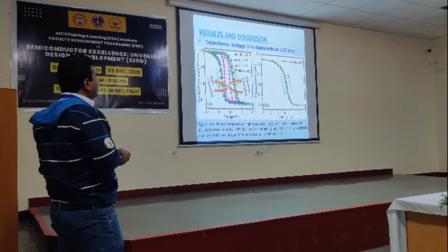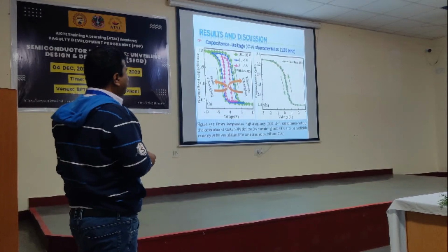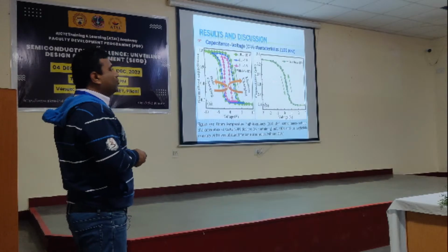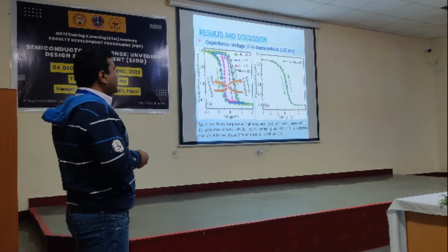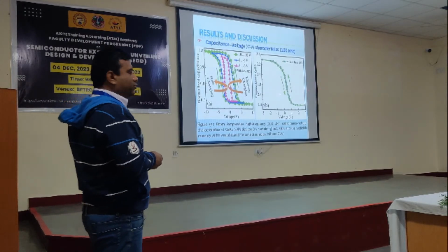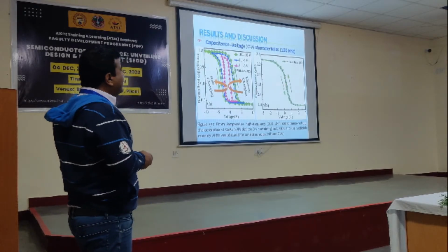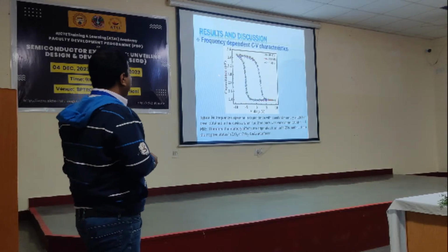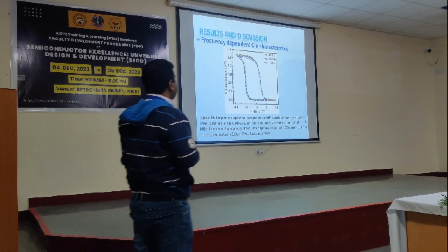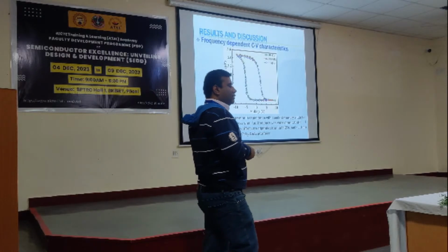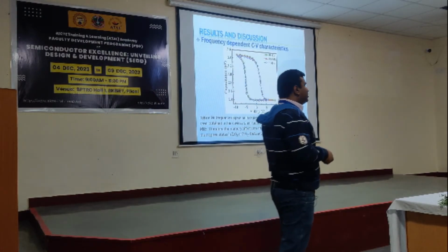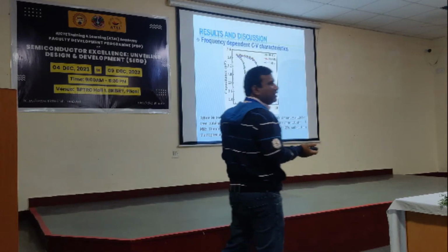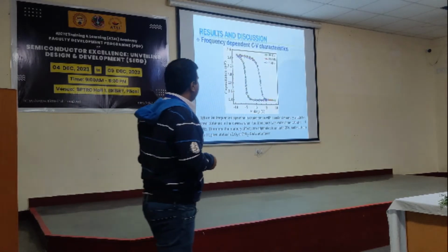And in the case where no quantum dots are present, you see a very small, negligible memory window obtained, because no storing element is there which is responsible for storing the charges. Here a very low hysteresis width is found. And again, as I told you, even if I minimize or passivate the surface with the gallium arsenide surface passivation layer, you see some little amount of interface trap charge is also already present.